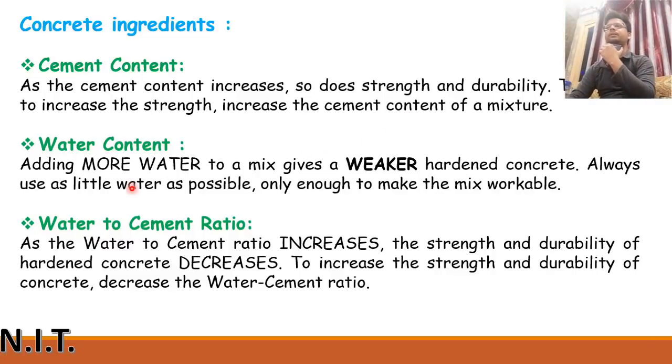What's water content? Adding more water to the mix gives a weaker hardened concrete. If you add more water in a concrete mix, you will get a weaker concrete. The strength will be very less. Always use as little water as possible, only enough to make the mix workable.